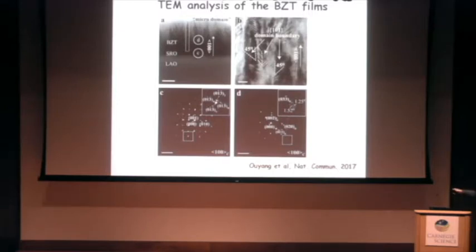This film is about 700, the scale bar is 200, so this is about 700 nanometer. You can see all these column-like structures. And then when you zoom in, you can see this nicely oriented zigzag kind of domain structure at 45 degrees with respect to the growth direction. So by just looking at the crystallography, you can tell all these are the higher order domain structure of rhombohedral.